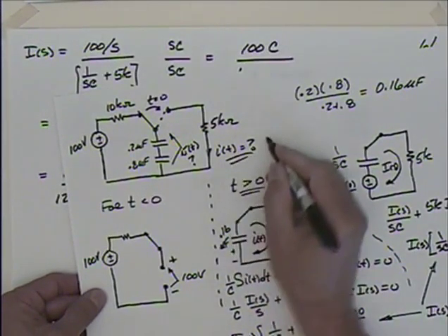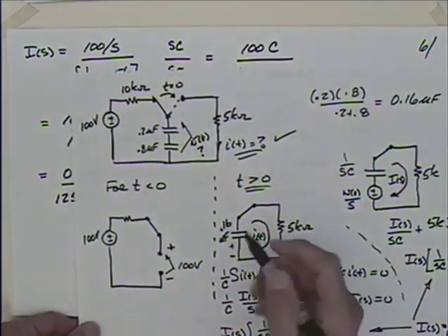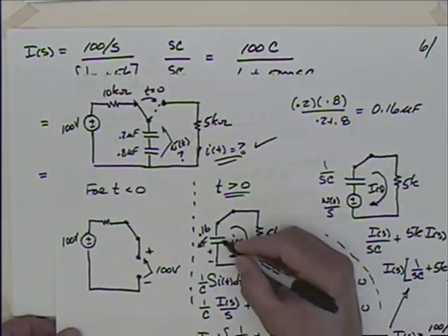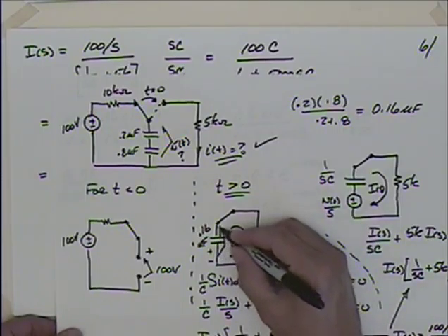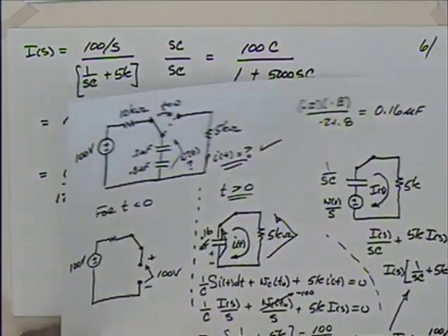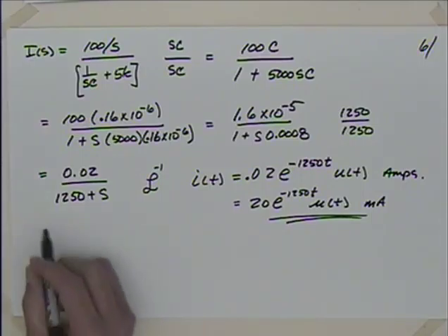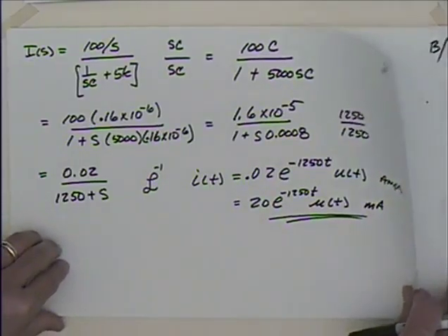We've got that then. Let's see if we can get the voltage across there. One thing to think about is that the voltage across the capacitor would be the same as the voltage across the resistor, because things in parallel are the same. So maybe I'll start a new sheet.